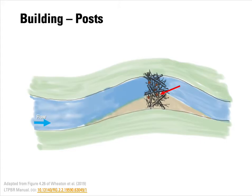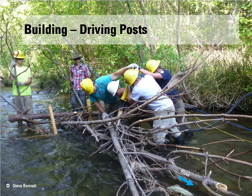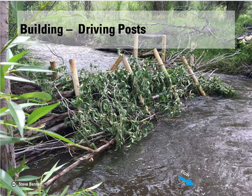And then, if possible, you pin the structure in with posts after you've got most of the shape made. The reason we do this is you are able to better lock the wood in place when you place the wood first and then drive the posts afterwards. It helps, especially with some of the larger material, if you angle the posts, and that stops the wood from floating up off your structure.